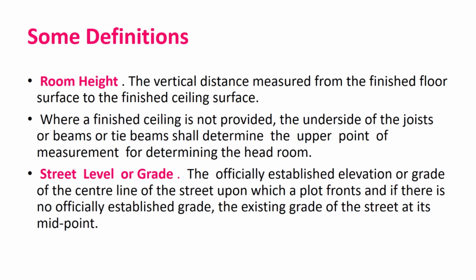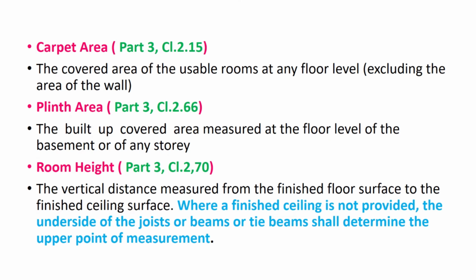Now suppose your founding level is 3 meters. So what they are saying is that 3 times of the estimated width, the foundation is suppose 3 meters. So 3 into 3 becomes 9. So whatever my founding level is there, I have to go that much below. This is I am taking something extra. NBC के अलावा I am telling this information.